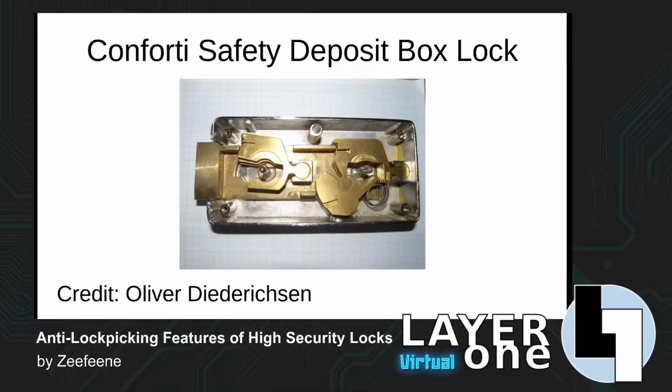But this curve on the edge of this lever is very cunningly designed, so that as we get closer and closer to the gate on the lower lever, we find that we are pushing backwards against that bolt stump. And if we want to set it correctly, we're going to have to allow that bolt stump to move backwards a little bit. And the problem there is if we allow that to move backwards a little bit, we release the lever above, and then they both drop, and then we have gotten nowhere. And so with any conventional picking tool, you will be caught in an infinite loop of set top lever, attempt to set bottom lever, and as you attempt to set bottom lever, release top lever, resetting the whole thing and having to start over.